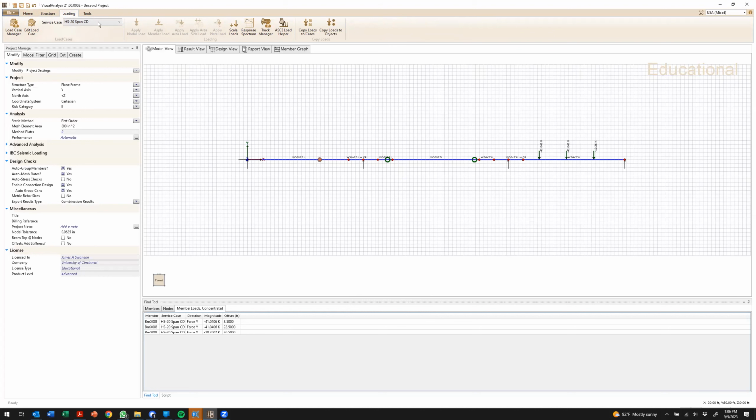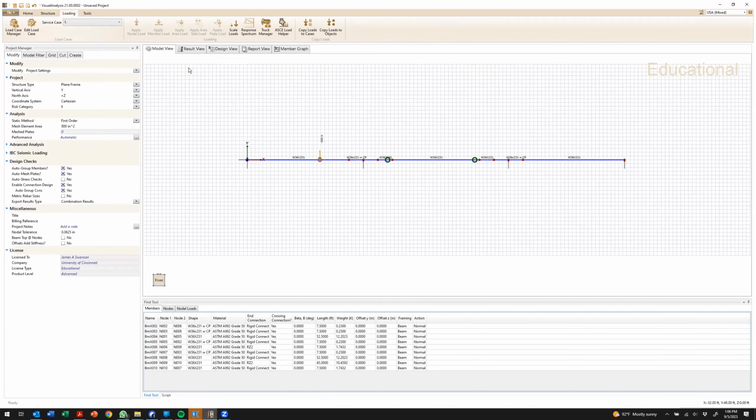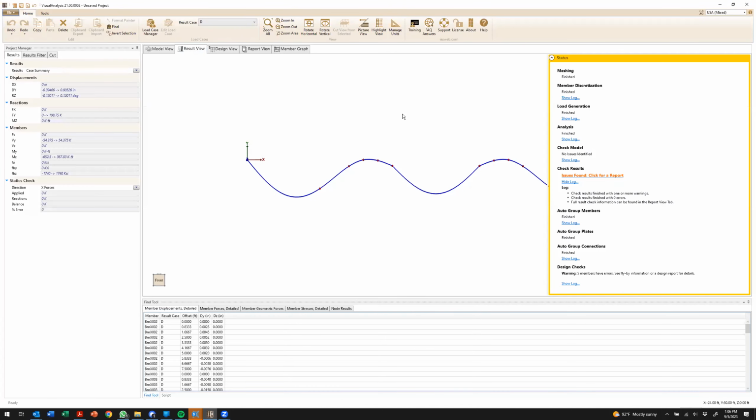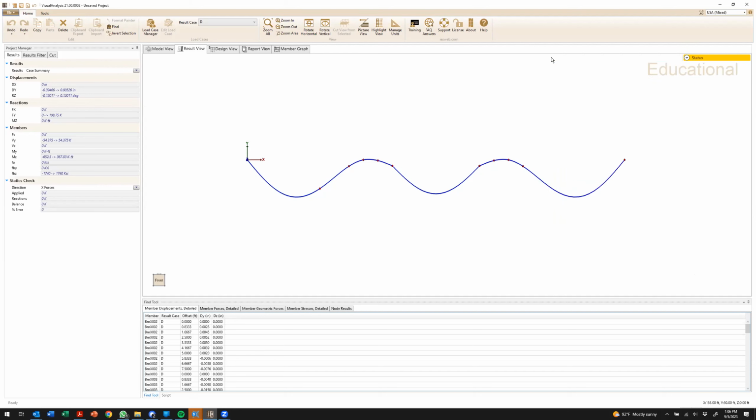All right, now let's look at that load case there. So if we go to the results view, it gave me an issue here. And so it automatically detected that node and said, yep, okay. So it was idiot proof enough. I was hoping that it wouldn't do that. That was just a node that wasn't connected to those members. It actually went in and connected it to the members automatically. Not all packages are going to do that for you, so you have to be careful. So the short answer is yes. Carson, good question. Any others?